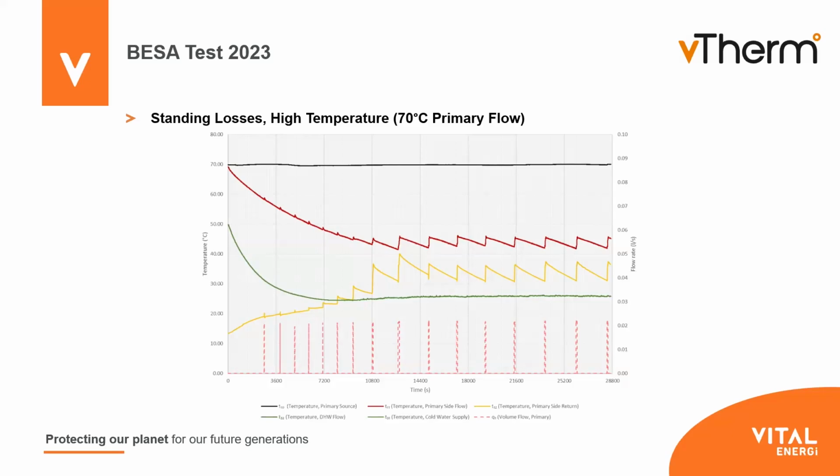One of the key things there is what that degrade time is. On this particular unit, our unit, we're talking anything between 32 and 42 minutes. Other manufacturers could be as low as 6 minutes. And therefore, you could be talking about excess usage of that valve actuator and therefore reduce the lifespan. So just be aware of that.